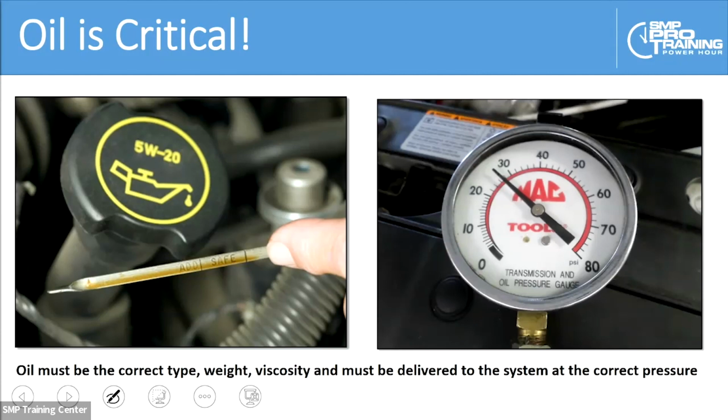If you think about it, we're using oil not just as a lubricant, but we're using it as a hydraulic fluid. So if this vehicle right here calls for 5W-20 oil, we better put 5W-20 in it. We don't want to put 20W-50 in this thing. Just imagine putting 80 or 90 weight gear lube in your floor jack. It's probably not going to work very well. So yes, we have to put the right weight of oil in the engine. In fact, some technicians will, as an early diagnostic step, go ahead and change the oil when in doubt.